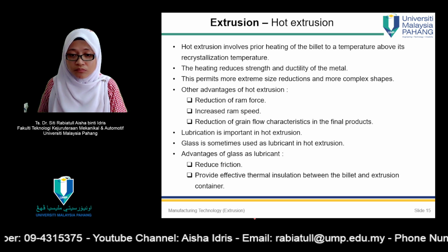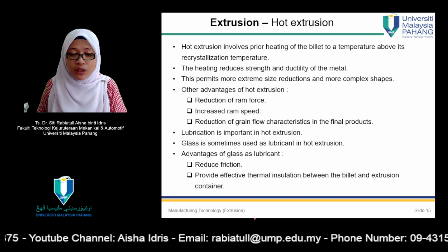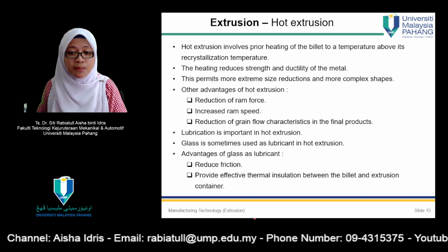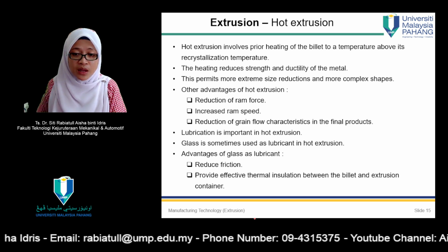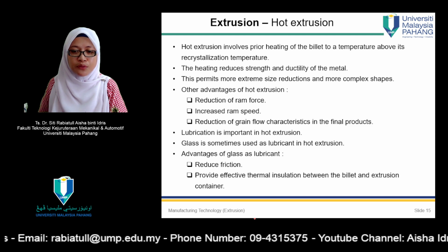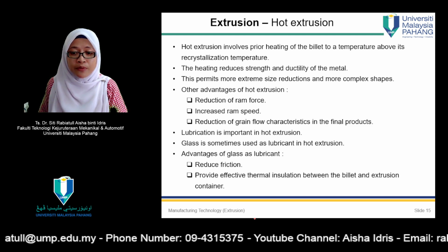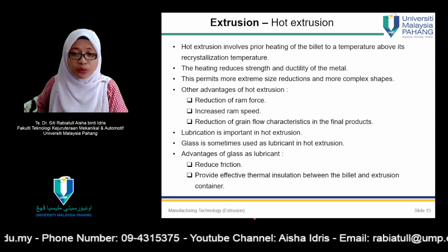What else? However, lubrication is important in hot extrusion. Glass is sometimes used as lubricant in hot extrusion. And the advantage of using glass as a lubricant is that it can reduce friction. It provides effective thermal insulation between the billet and the extrusion container.